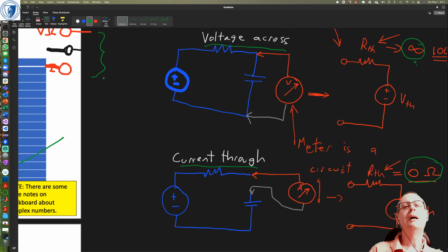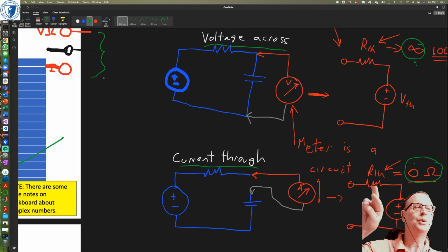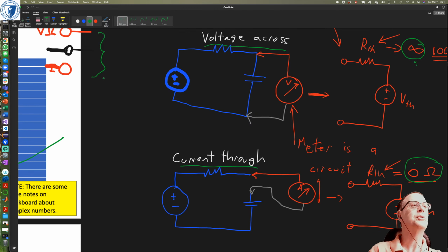The easiest way to change from high impedance to low impedance is to use separate terminals, but the mistake you'll make is you'll put the meter on measuring current, but your probes will still be in the voltage measuring inputs.